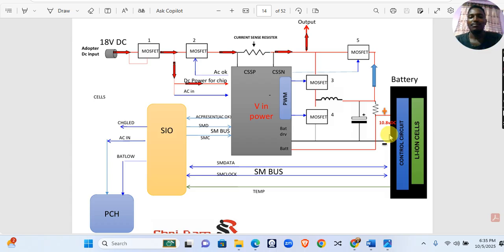for charging the battery. So maybe your issue will be the MOSFET, or the charging IC. This IC must give the correct signals and must give instruction to this MOSFET to switch the correct voltage. Alright? Yes, in case you have less voltage switched from here, it might be an issue with the IC or an issue with the MOSFET. Then, still you need to check whether these MOSFETs are shorted, especially the charging IC, the charging MOSFET.